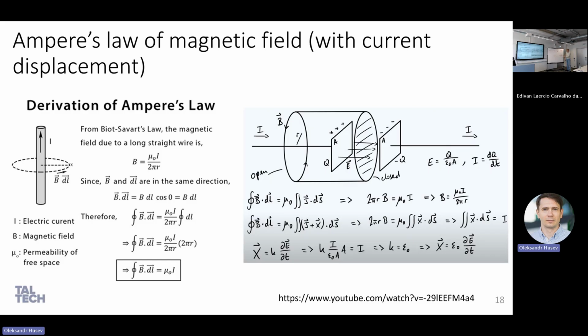And this is the basis of, again, how you calculate inductance. But inductance can be air-core, doesn't matter. Of course, if you use ferrite and you enclose your magnetic field inside the ferrite, mostly it's much easier to define. FEM analysis is usually used: if you use ANSYS to simulate, it calculates the magnetic field at each point by this law of superposition. That's why this basic equation is quite complex, but you can calculate for any shape. You just need to define the magnetic field for each coordinate and then calculate along this path.